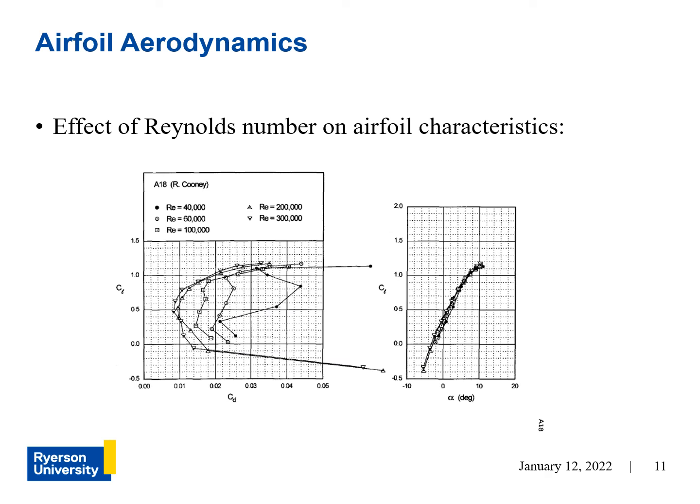Alright, so here we'll see the effect of the Reynolds number on the airfoil characteristics. Notice how at different Reynolds numbers, the drag characteristics of an airfoil change drastically. Here you can see the plots for the different Reynolds numbers, represented by different shapes, and you can see that the drag polar is heavily affected.